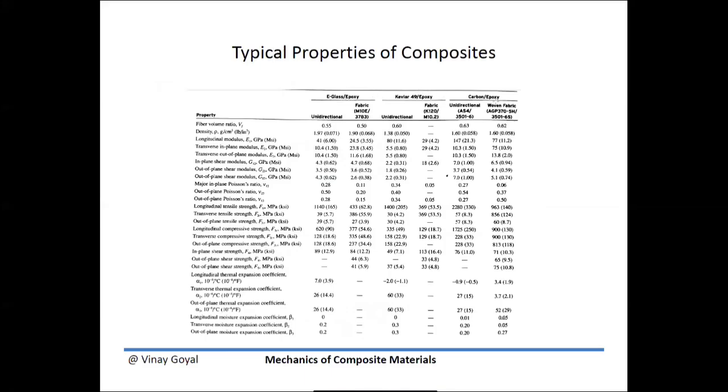Feel free to pause the video and look at this carefully. But I hope through this video lecture, in summary, what we've done, we've learned how to take a 3D problem and use classical plate theory, which is making fundamental assumptions that the plate will be thin, that if I were to make it thin, I can just track the mid-surface. And if I can solve for the deflection of the mid-surface, then I can solve for the ply stresses and strains, which are important to determine whether the structure will fail or not. That's how you will size it, right? You want to size it to make sure you're not failing the structure.